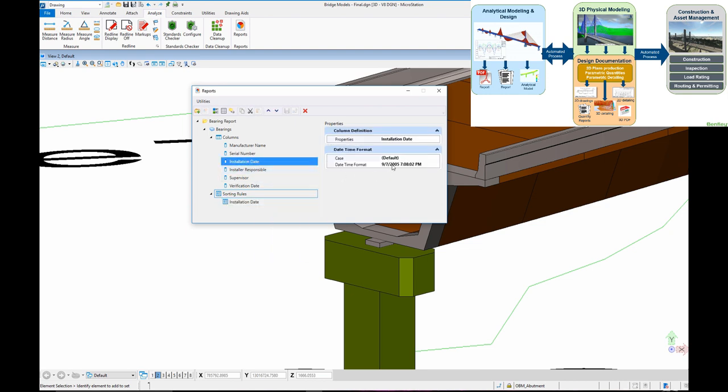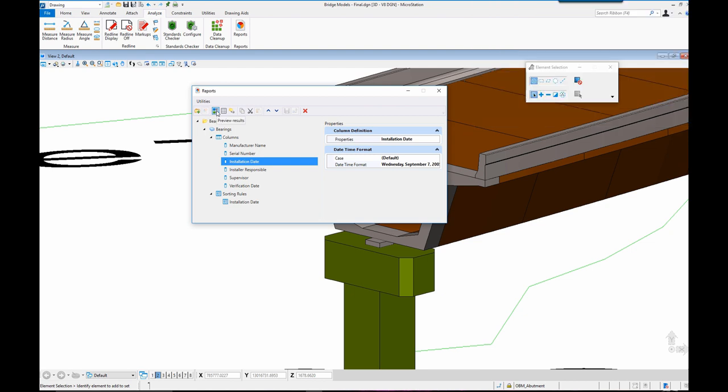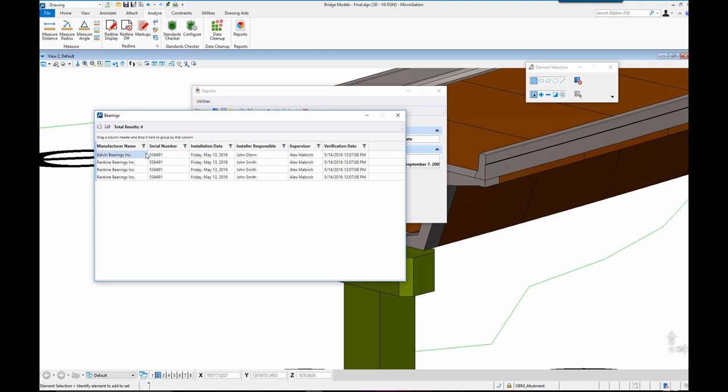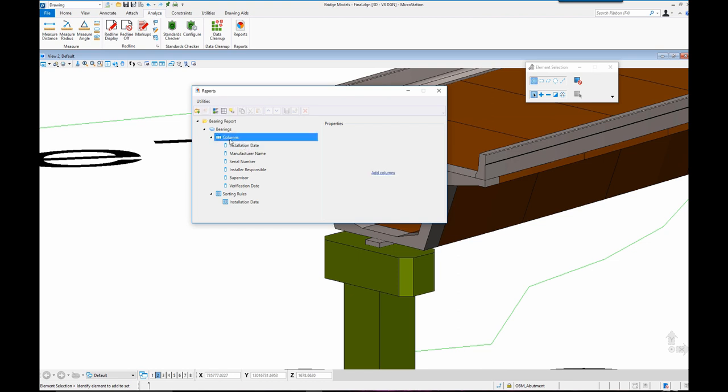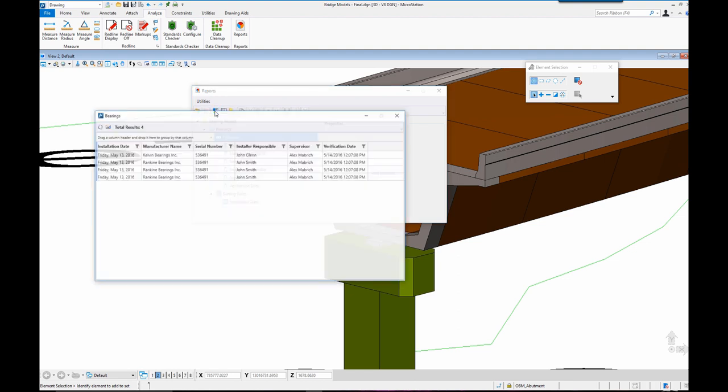So the model that we create is also prepared to receive information that is not particularly related to design. What if I want to enter into my model information about construction, inspection dates, specifications, as I said, information that is not part of design? Through the use of Bentley item types, we can add this information that is not particular to design, but at the same time becomes part of my model. It's the same model being enriched at every phase, with more and more information that will come from the software itself, like analytical information, but also information that pertains only to our practice.